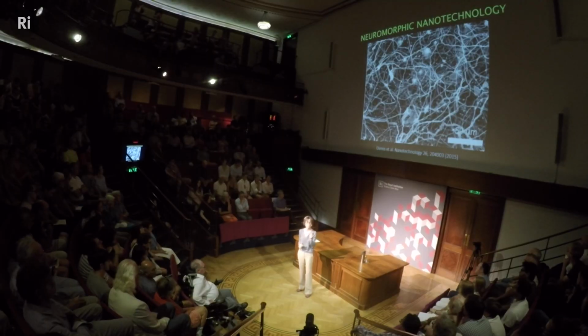But secondly, in addition to the network structure that these nanowires can produce, it turns out that because they form this complex network, they actually overlap in many, many areas. And the locations at which the nanowires overlap with each other, when you put an electrical stimulation over the network, they actually behave in exactly the same way as synapses do, in the sense that where two wires overlap, they form a junction. There's a gap between them. And when that junction experiences an electrical stimulation, it actually drives ions from one wire to the other in exactly the same way that neurotransmitters are transmitted across synaptic connections between neurons.